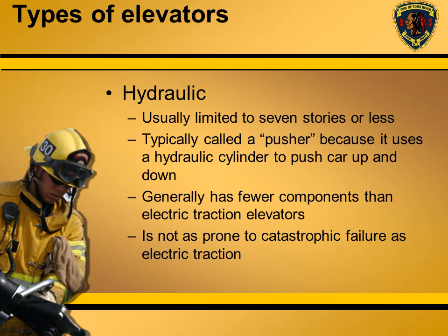Elevators come in two basic types: hydraulic or cable. The response to stuck elevators is the same for both a hydraulic elevator or a cable elevator. The difference is that for most firefighters, we do not have the adequate training or equipment to lower a cable elevator. We are able to lower most hydraulic elevators using a few simple steps.